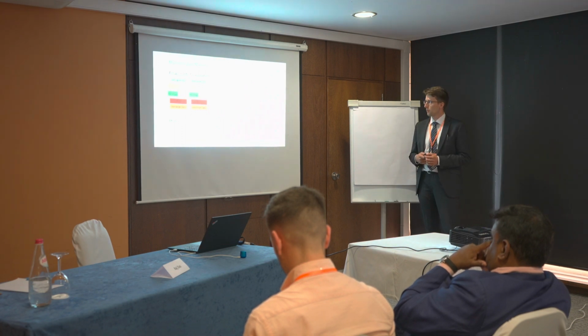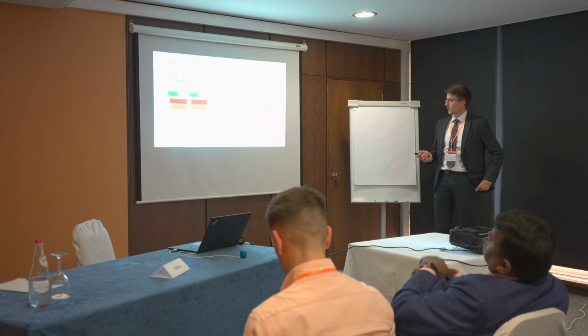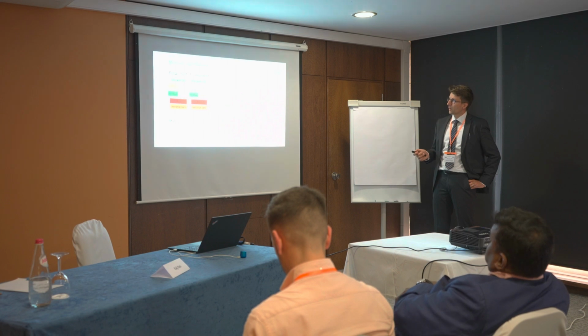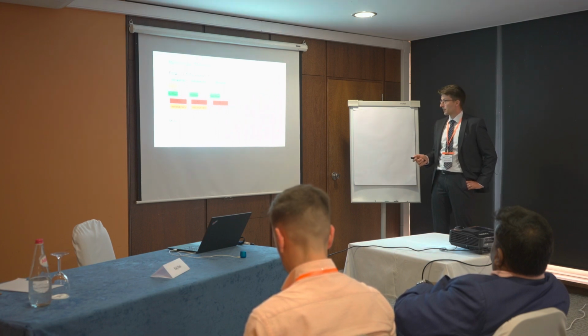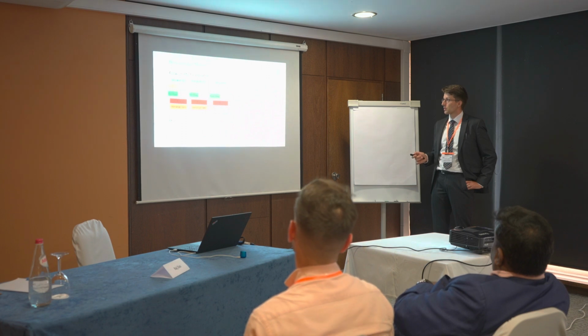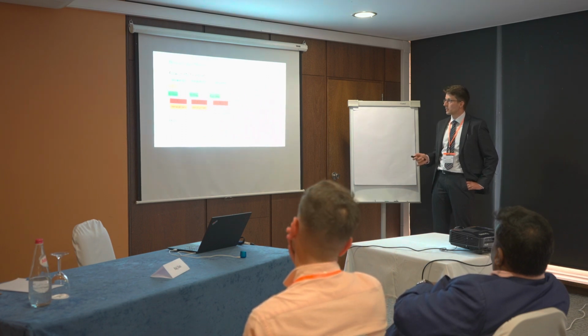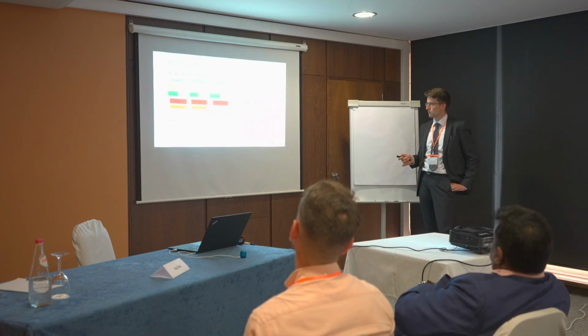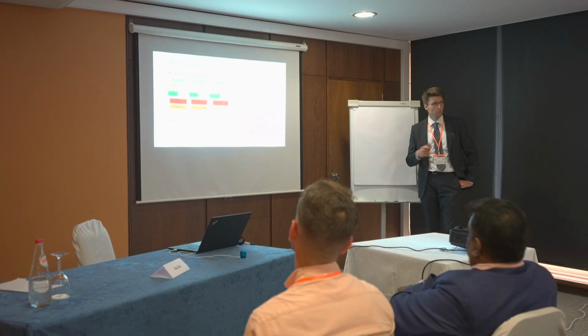Then we have to perform bars apart again with the transmission bar, or transmitted bar. We also have to measure these things again, rearrange, and then we put the bars together, and we have to measure the strains in the bars with these calibration factors, and we have to calculate a transmission factor, and then we can perform an actual test.